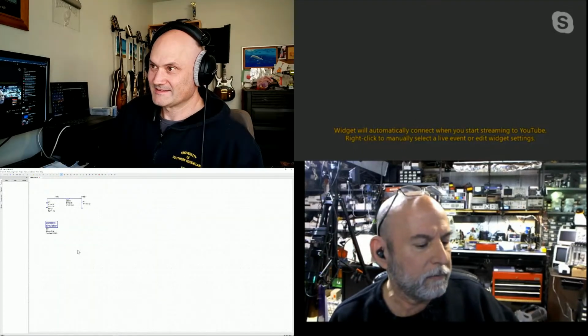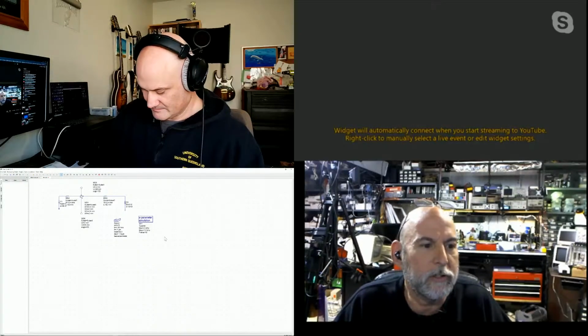So yeah, Mike, what we were talking about was gain and transistors the other day. Oh, Mike, I remember what it was. You built a video buffer. I've used like the AD812 and stuff. But what I was going to tell you is your op amp is probably a current mode op amp, if it's a true coax line driver, 50 ohm, versus a voltage type of op amp. They are different critters. So, a transimpedance amp?